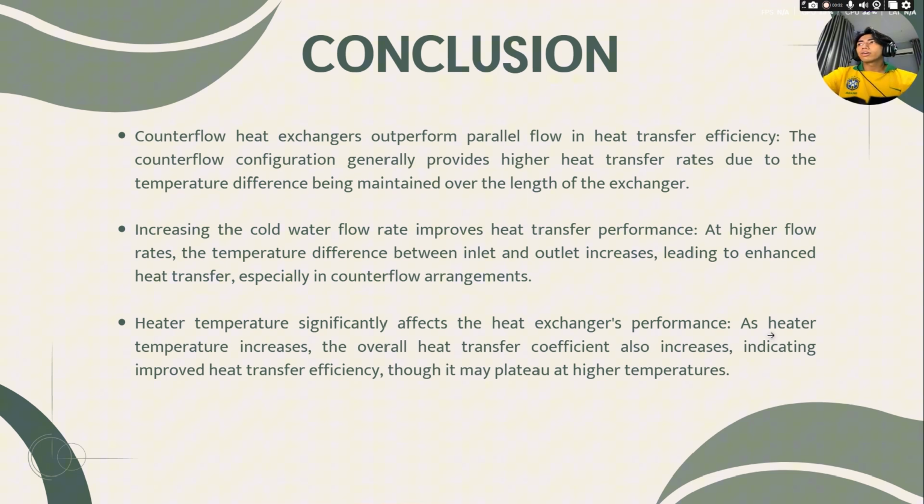At higher flow rates, the temperature difference between inlet and outlet increases, leading to enhanced heat transfer, especially in the counterflow arrangement. Third, heater temperature significantly affects the heat exchanger's performance. As heater temperature increases, the overall heat transfer coefficient also increases, indicating improved heat transfer efficiency, though it may plateau at higher temperature.